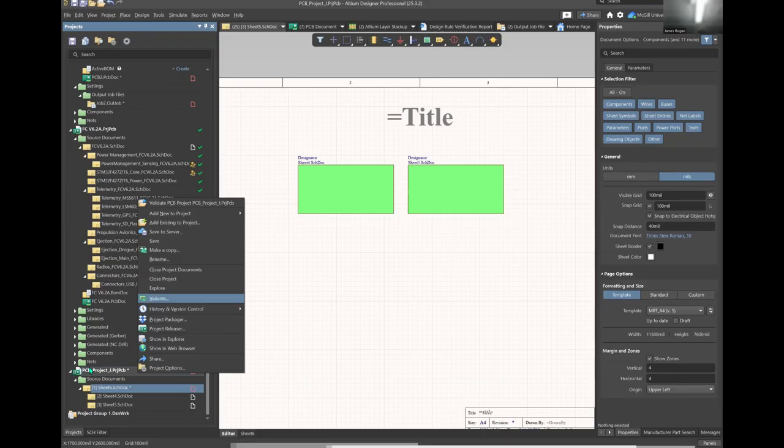You have your little squares drawn on schematic 1. Which one do we choose? You just pick a top level sheet and then add the sheet symbols to that. How do you add the sheet symbol? There's a tool in the top bar here. It's just this green one here.